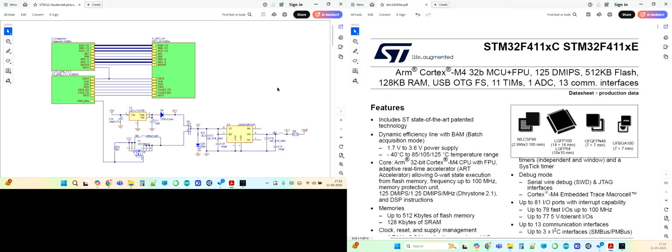Hope we gave a glimpse of how power is distributed in the STM32 Nucleo board. Please post if you have any questions. So we specifically suggest, when you are using the Nucleo board, use a multimeter, probe across different points of this STM32 and get to know the main power points and measure with your multimeter, so that you get good hands-on experience and also clarity on what all power distribution is happening on this particular board.